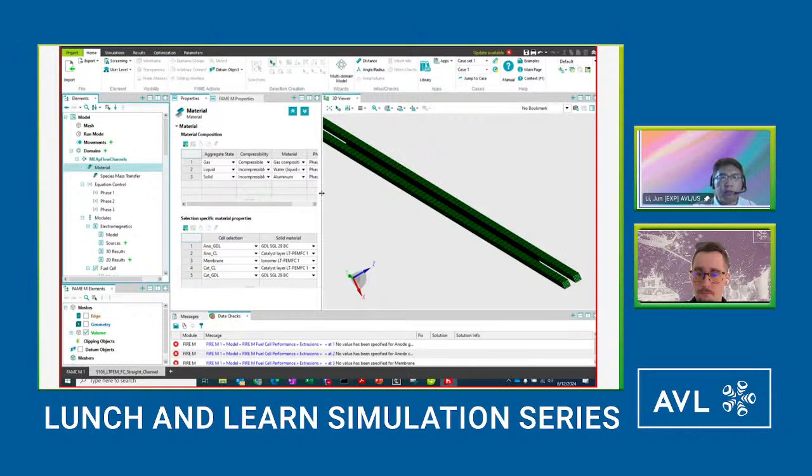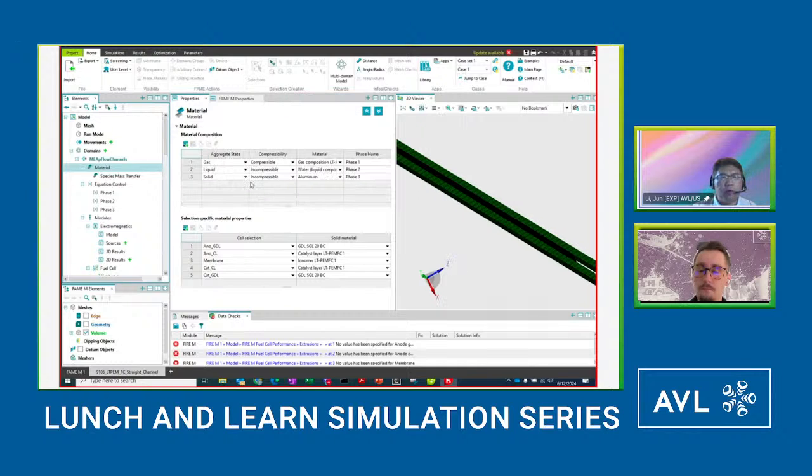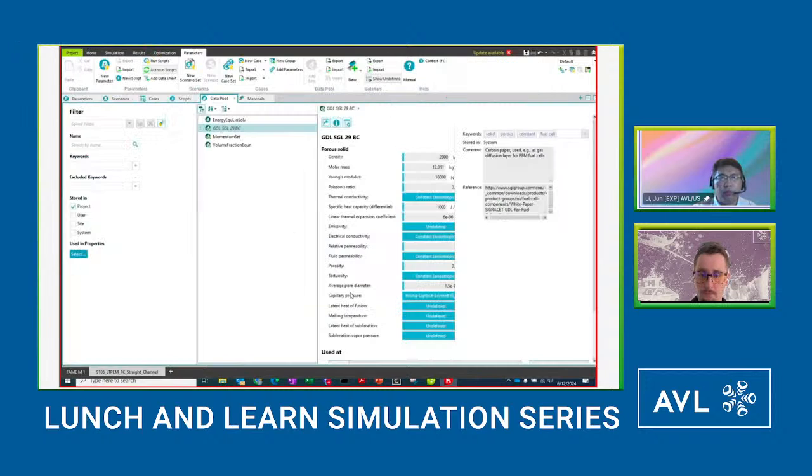The first thing we need to specify is the material for this simulation. We have three materials: gas, liquid, and solid. In terms of the solid part, we have the GDL, the catalyst layer, and the membrane, and the GDL and catalyst layer for both the anode side and cathode side. Then you can specify the solid material, either choosing from a database. For example, I show it in the material section here, and then the user can copy and paste this and modify it according to their own needs.